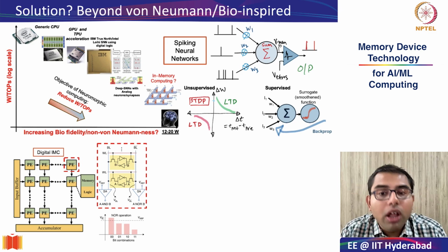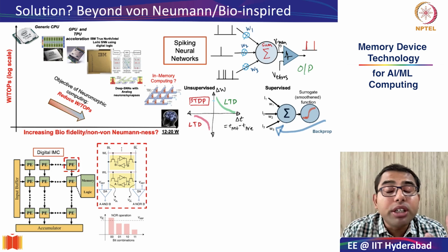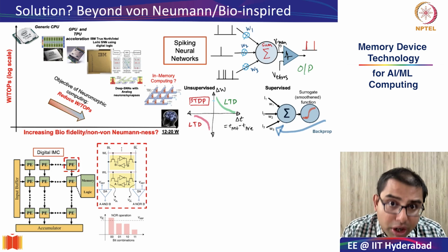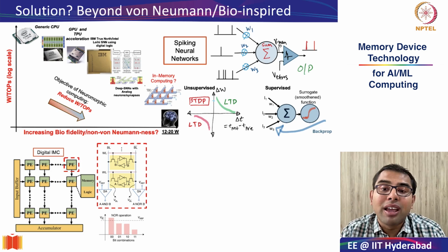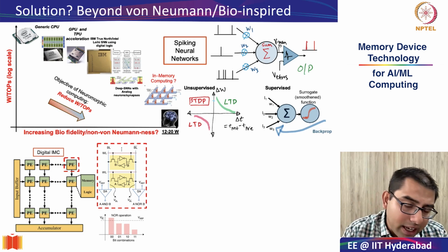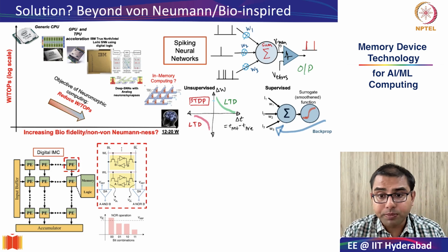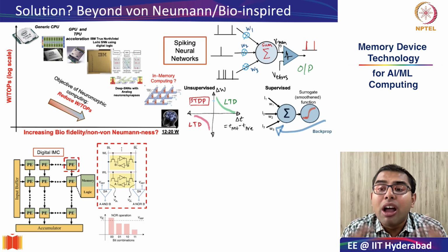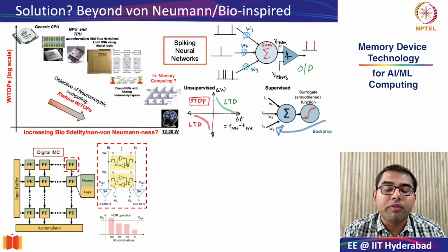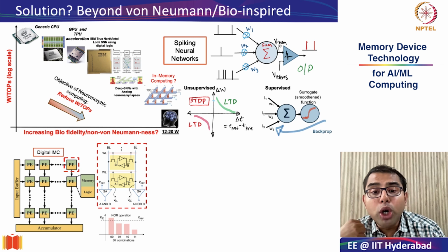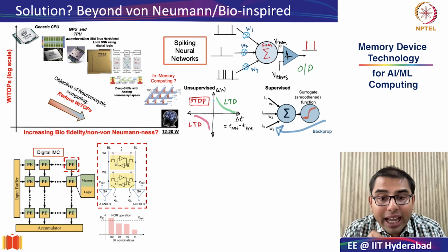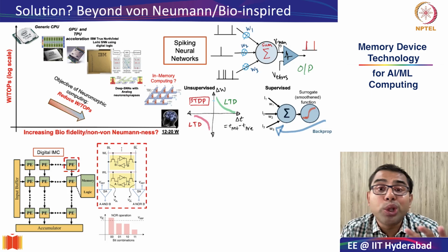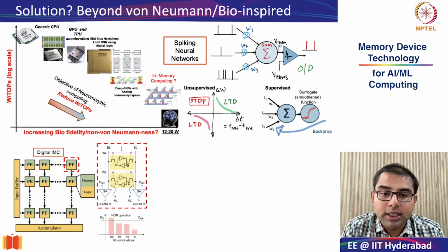And this is where the paradigm of digital and analog in-memory computing was introduced at the last part of our course. So as you can see, in digital in-memory computing, we compute by performing Boolean logic within the memory array itself. And this we are able to achieve by cleverly modifying the peripheral circuitry and also the pulsing protocols.